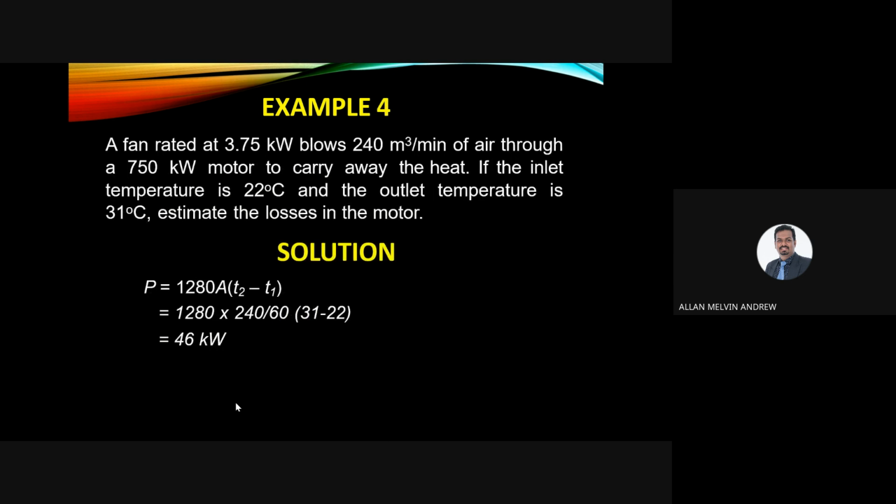So another example: a fan rated at 3.75 kilowatt blows 240 meter cube per minute of air through 750 kilowatt motors to carry away the heat. If the inlet temperature is 22 degrees Celsius and the outlet temperature is 31, estimate the loss in the motor.